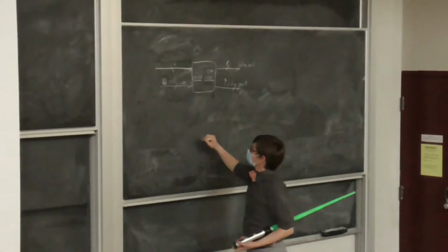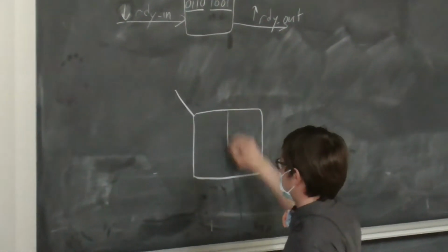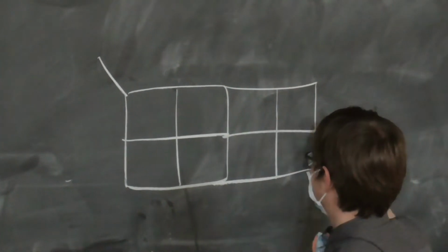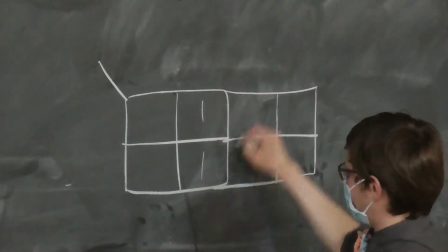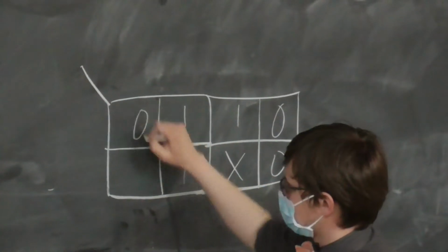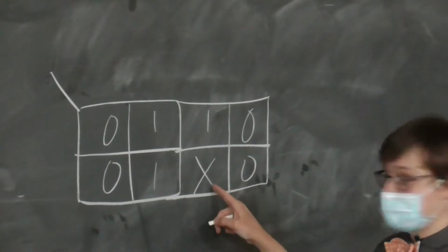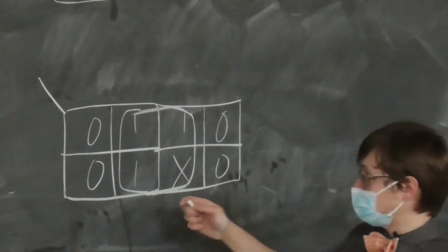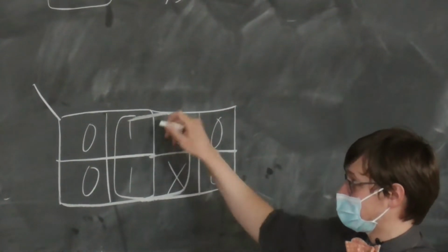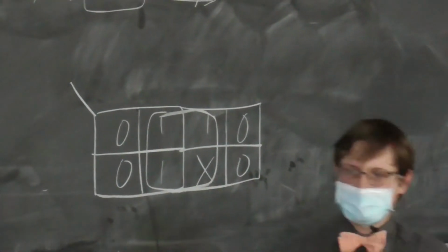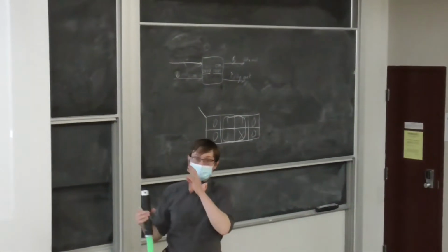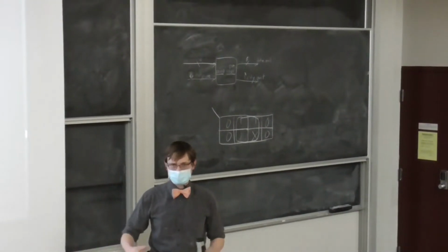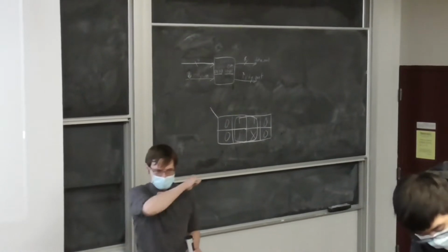Consider a Karnaugh map, right? Let's just do a small, simple little one, right? Let's say, well, now let's do a slightly larger one. Let's say you had 1, 1, 1, x, 0, 0, 0, 0. Because this is a don't care state, you can do a Karnaugh group that includes it, which means that you can simplify the logic quite a lot, because that's a lot simpler than the two groups, right? So with don't care states, you can arrange them in such a way that it minimizes the number of state logic gates that you need, right? Does that make sense? Yeah, awesome.